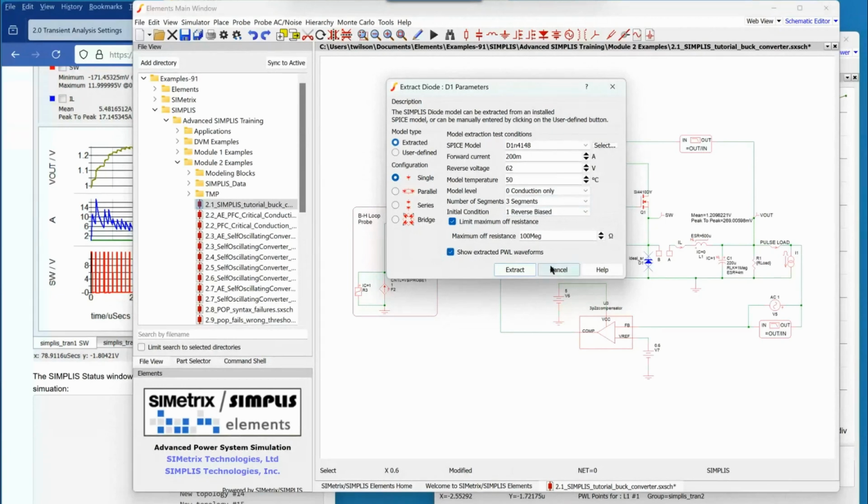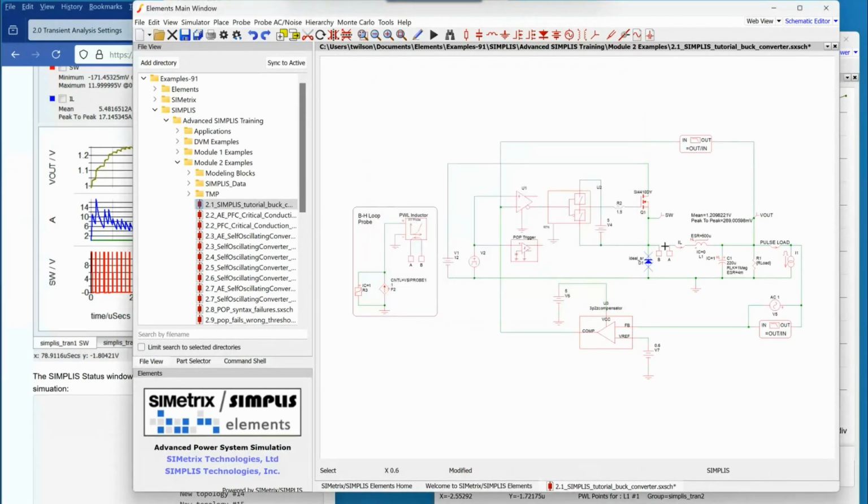But if you're careful, you can do a 2-segment diode. If you think about it, every combination of these piecewise linear segments that you actually encounter in the circuit is a new topology. So it's not like this is 2, this is 2, this is 2, but it's all the different combinations.